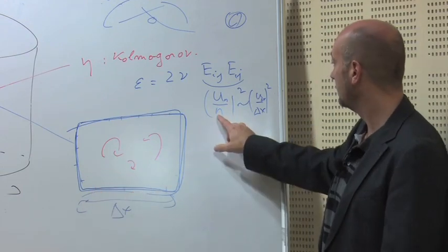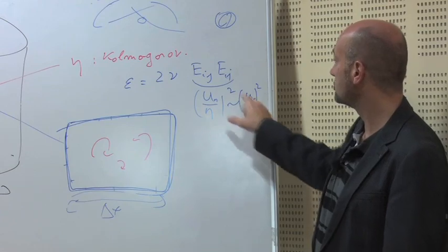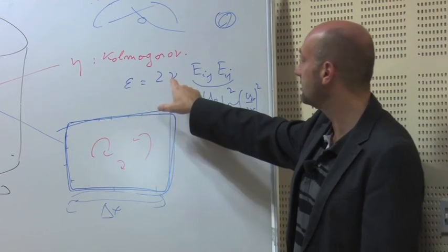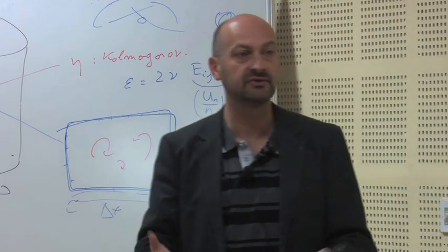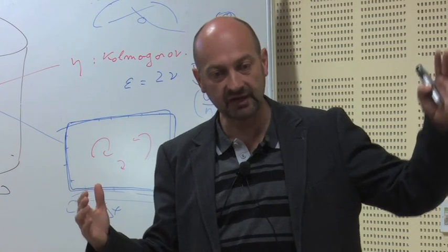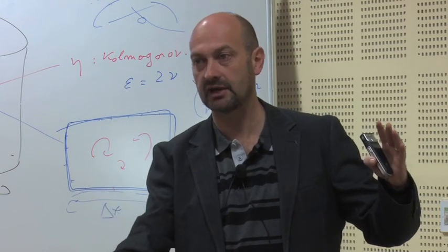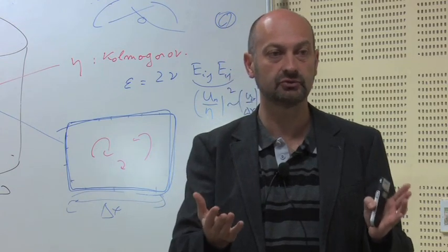If delta x is larger than eta, that term will be smaller than what you expect, so you multiply by a larger viscosity to keep the good rate of dissipation. If you then have the correct output, your simulation has more chances to be correct.